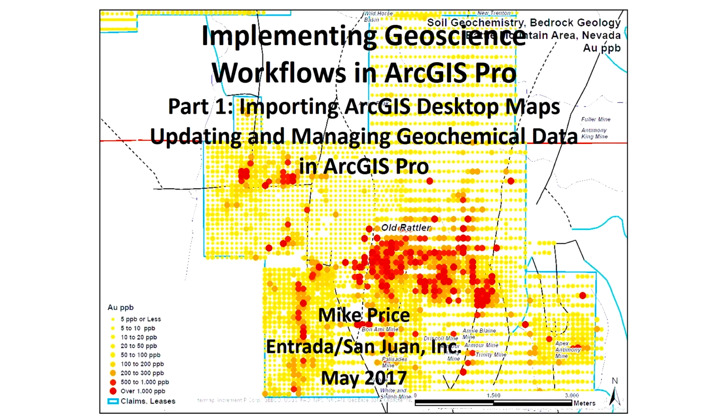Yeah, cleaning data is really important. Any kind of documentation that you've been doing traditionally using ArcCatalog for your metadata, for example, building thumbnails, continue to do that on the desktop side because those will come into Pro as well. So definitely clean up your data, make sure your maps are consistent, you don't have coordinate system issues, your bookmarks are well defined and documented. Definitely take a very objective look at your map before you import it.